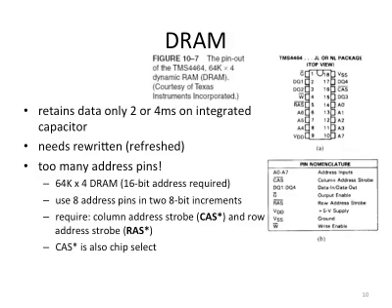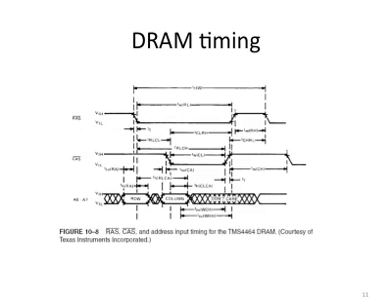For data, we have DQ1 through DQ4, a 4-bit input and output. And of course, we have write enable, power, and ground. Here's the timing diagram that shows how this chip operates using these 8-bit address lines, the row address strobe, and the column address strobe.